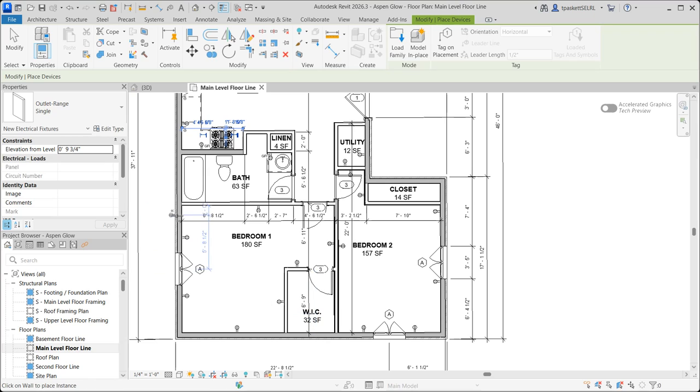Okay, all right. So you're going to do that in all the rooms. Again, 12 feet apart in most cases. In the kitchen, 4 feet apart, so we have enough. If there is a wall that's 2 feet or more, then you're going to put one in right there. And again, I've got a door there that's going to go on there. So put those outlets in.